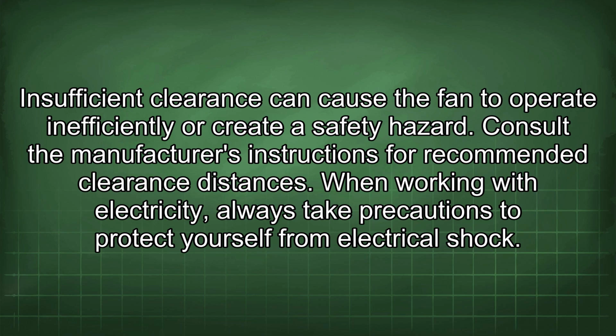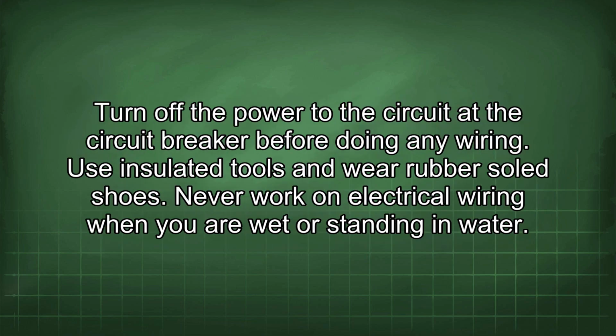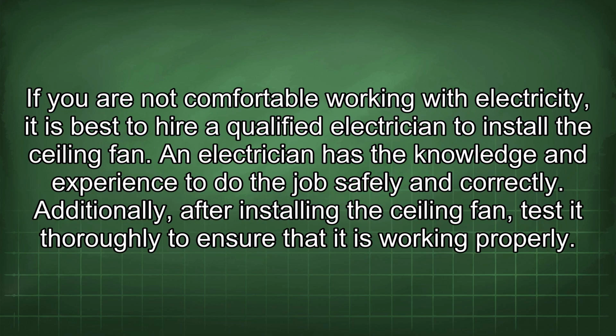When working with electricity, always take precautions to protect yourself from electrical shock. Turn off the power to the circuit at the circuit breaker before doing any wiring. Use insulated tools and wear rubber-soled shoes. Never work on electrical wiring when you are wet or standing in water. If you are not comfortable working with electricity, it is best to hire a qualified electrician to install the ceiling fan. An electrician has the knowledge and experience to do the job safely and correctly. Additionally, after installing the ceiling fan, test it thoroughly to ensure that it is working properly.